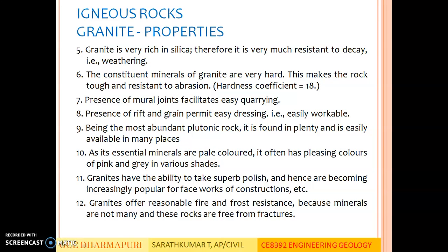Granite is very rich in silica, therefore it is very much resistant to decay, that means weathering. We have seen in the mineralogy topic, of all the rock forming minerals, only silica is very resistant to weathering. All other groups of minerals, like feldspar group, mica group, hornblende, amphibole group, are easily subjected to weathering. Upon being subjected to natural agencies like river, wind, etc., these minerals will undergo disintegration and break easily. Whereas silica is very much resistant to weathering due to its structure and texture.